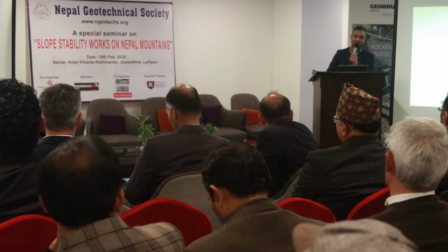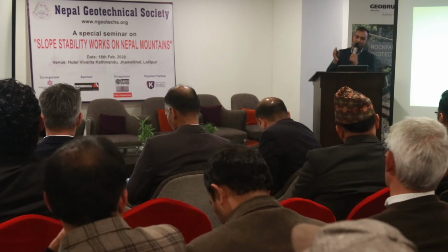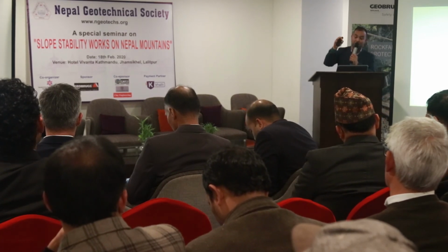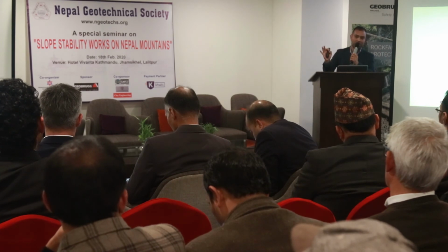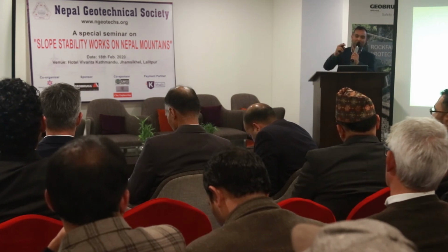And for the case I just showed, the road section, it has rock outcrop every 10 meters, and in the middle there is colluvium. So where is the failure plane? We put uniform homogeneous material all the way down and use the software. So you can judge it. You are our geotechnical engineers.